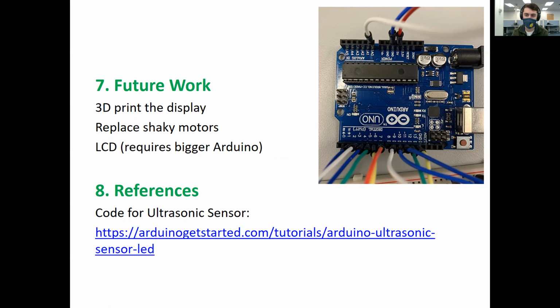Problem with that is I'm gonna need a bigger Arduino board. Currently, I only have 3 digital pins left, and the LCD requires, I wanna say 8. I would have to pull out all of the other LEDs in order to have the minimum required pins for the LCD. But if I wanted them to work together, then I need a bigger board.